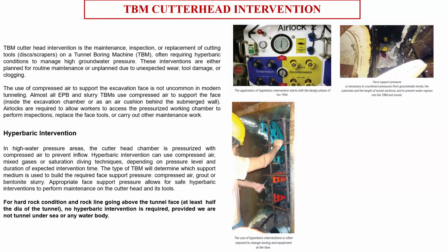Nowadays they mostly follow the curve pattern. It is preferable that the shield and the segments mostly follow the curve pattern. That is why you always use a universal ring, with taper on both sides, so that it always tries to follow the curve pattern of the alignment. So the shield and the segments are almost in the same line.